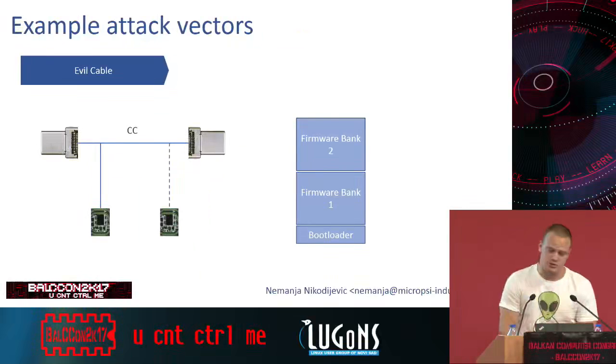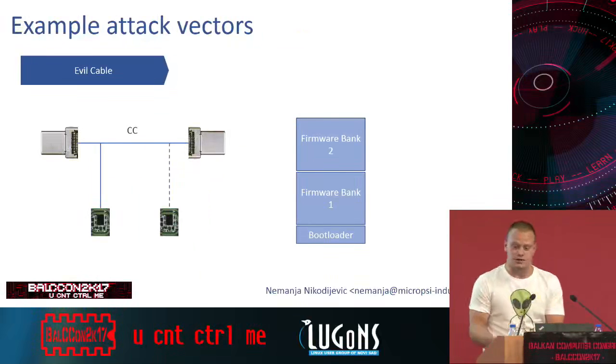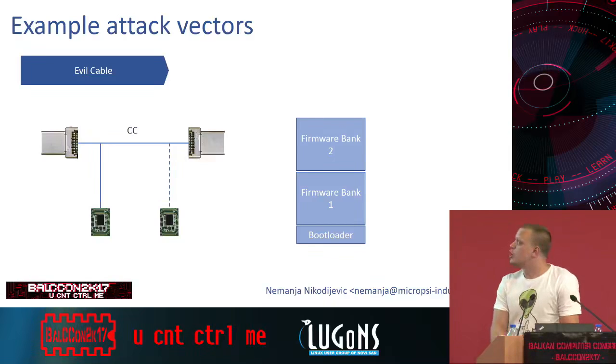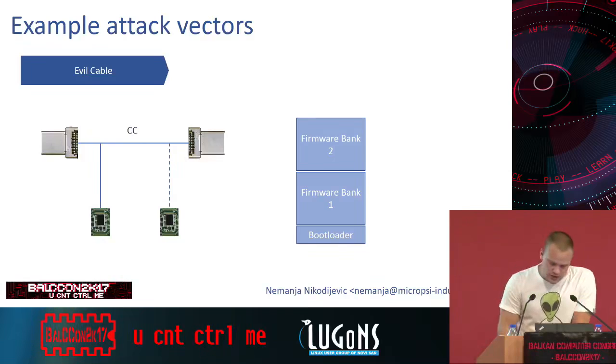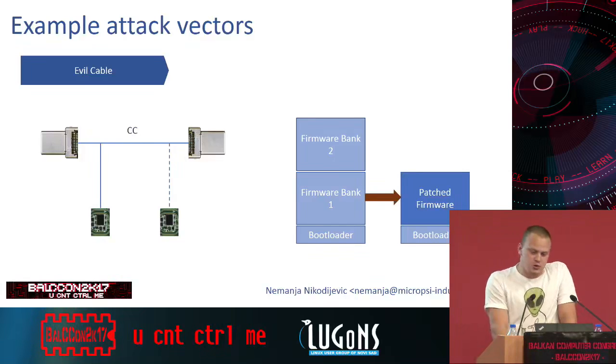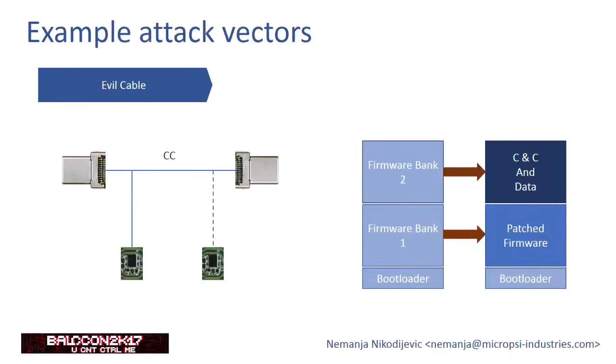There is a bootloader and two firmware banks, because you don't want to brick your cable. Like if it's upgrading and you unplug it, then it's completely useless. So what if you can use tools provided by these chip vendors to patch the firmware and use another bank for sending command and control and data information.